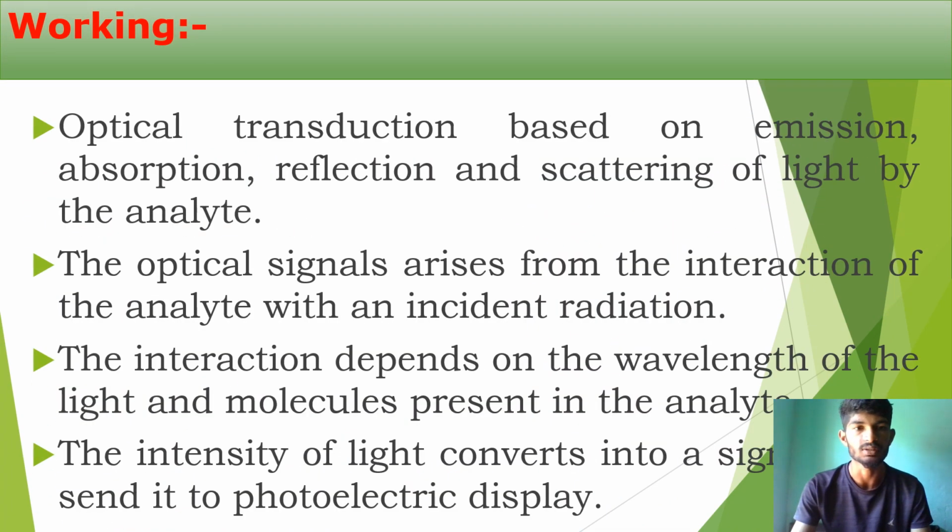Working of optical sensors. Optical transduction is based on emission, absorption, reflection and scattering of light by the analyte. The optical signal arises from the interaction of the analyte with the incident radiation. The interaction depends on the wavelength of the light and the molecules present in the analyte. The intensity of light is converted into a signal and sent to the photoelectric display.